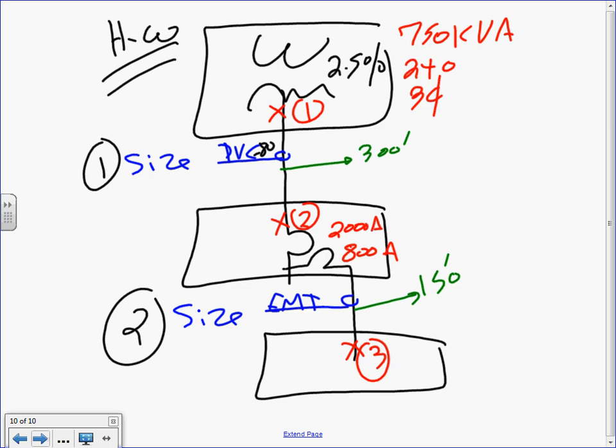You're going to size it. I have 2,000. How are you going to? Would you pull one run to 2,000? That would be big. I don't think you can find a conductor anywhere. For the 800, you have to parallel. Both of them you have to parallel. The rule when we size, guys: you don't want to carry more than 400 amp in a feeder. So I make sure that I divide this by 5, I divide this by 2, and carry the conductors. Okay? Any comments, any questions, guys?